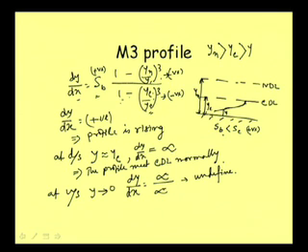So, if we want to draw something here, we can put a dot, a dotted line, indicating that we are not sure what will happen as it approaches 0, and then this profile will be rising like that and meeting the CDL line normally. That is the characteristic of the M2 profile, and this is of course a rising profile.